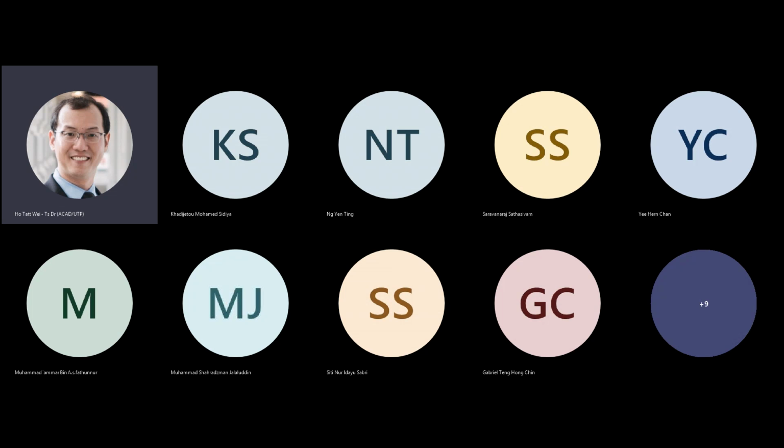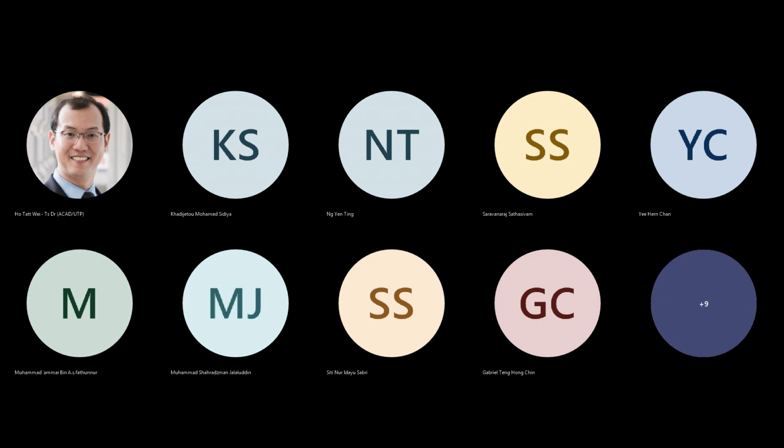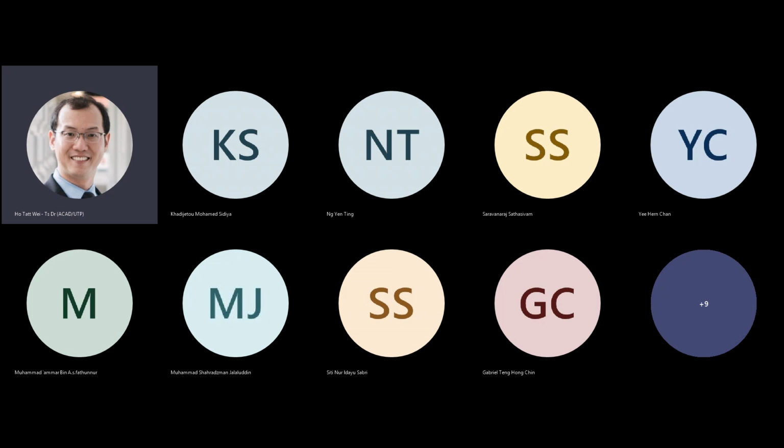So we are essentially moving towards a model where we convert your MOSFET into an equivalent resistance R, and then there is a capacitance to ground here sitting at this terminal, and it's also the sum of the capacitance sitting at this terminal of the MOSFET, so the sum will be here. And what is this? This is a resistive capacitive network. We can use this as an effective charge and discharge of the capacitance to estimate the delay of logic gates. That's where we're going with this.